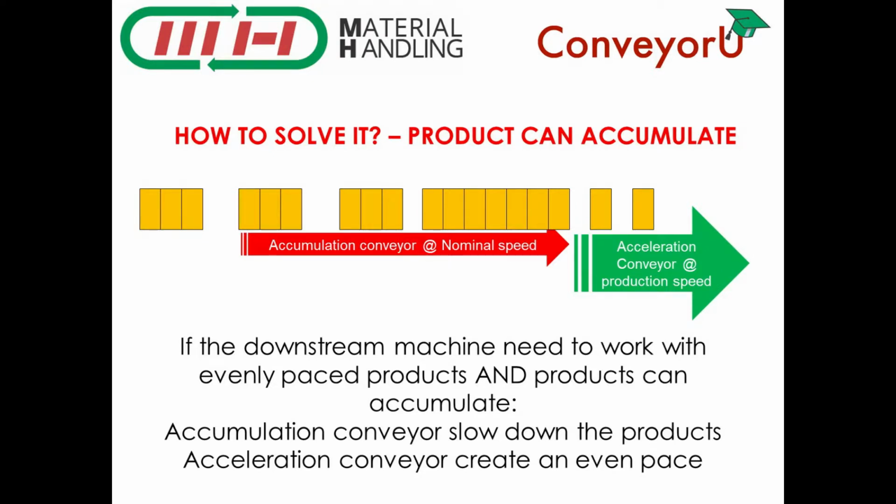We just need to place an accelerating conveyor after the accumulating one. So we will have the accumulating conveyor running at the nominal speed. We will have a very small accelerating conveyor after this one, running at twice the nominal speed. So once the first product of the train passes from the accumulating conveyor to the accelerating one, this will immediately create the gap that we need. So this allows us to rephase the product and regularize the pacing of the products in a very easy way.